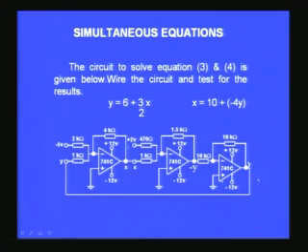Corresponding to the second equation, you can see in the next op amp, you have 1.5 kilo ohms and 1 kilo ohm, and so the ratio is 3 by 2 times x, that x is connected here. So 3 by 2 x with a negative sign here, I will get minus 3 by 2 x here, and this is 470 ohms, which is close to 500 ohms, and this is 1.5, therefore it is 3 times.